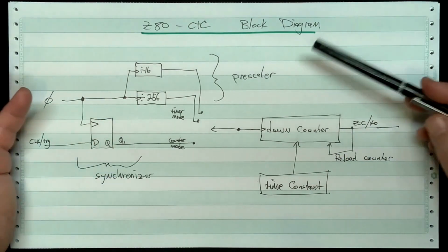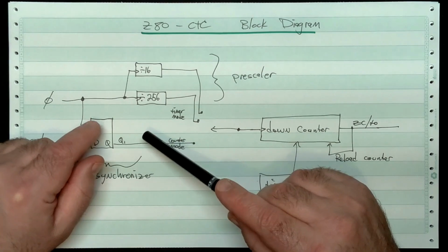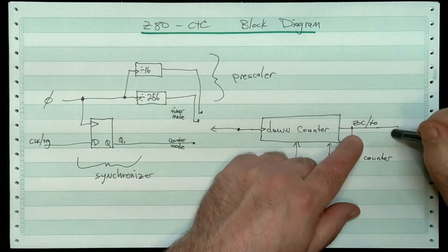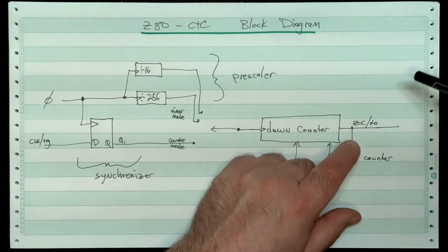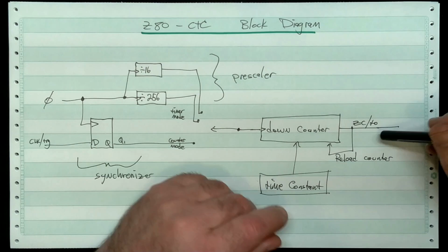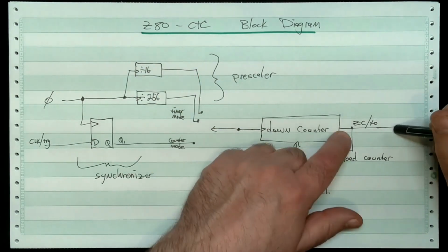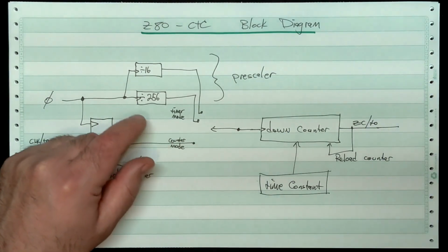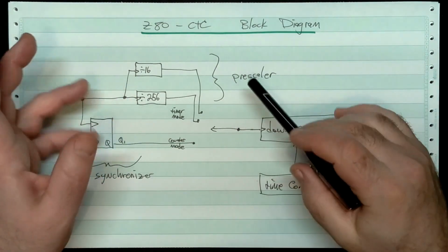So usually the whole point of these things running in timer mode anyway is to generate a periodic pulse over here so you can measure the time of day or something. So if we were going to use this to meter out and get like a 1 kilohertz signal out of 10 megahertz, you need to divide that by a pretty big value. My point is, you're usually dividing by big numbers anyway.